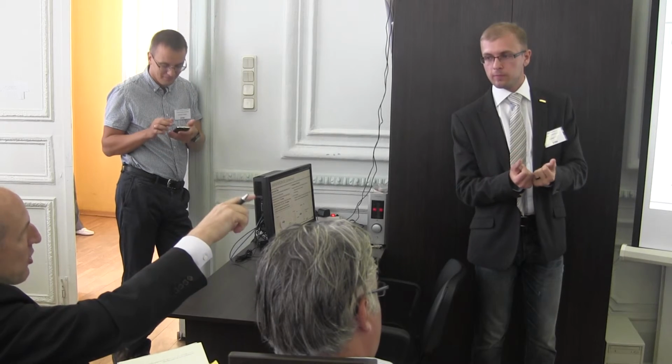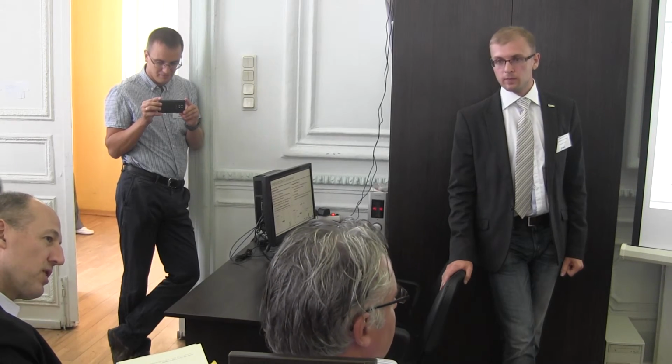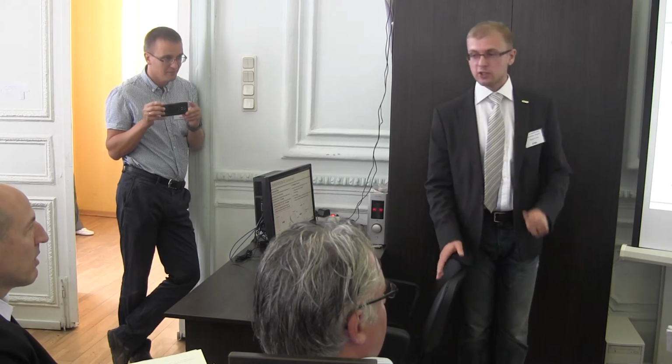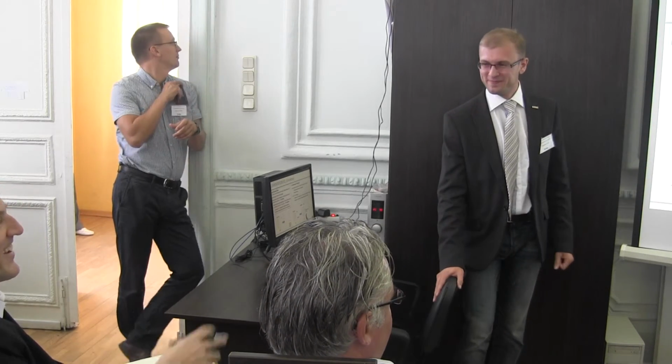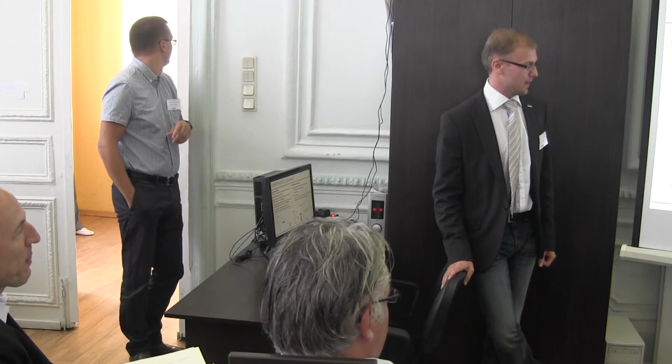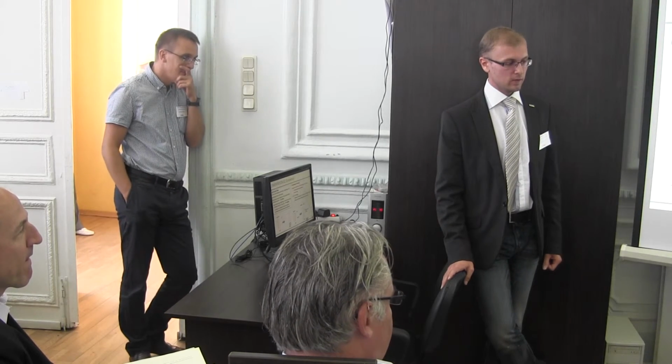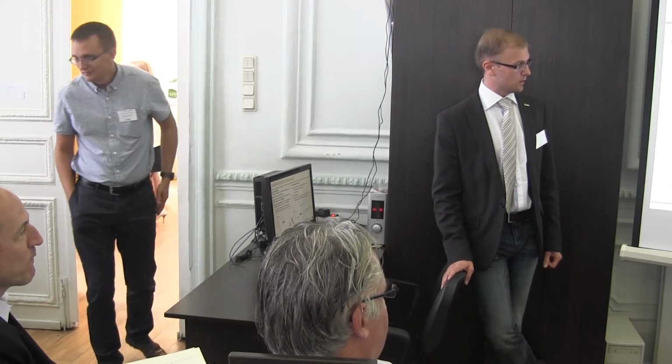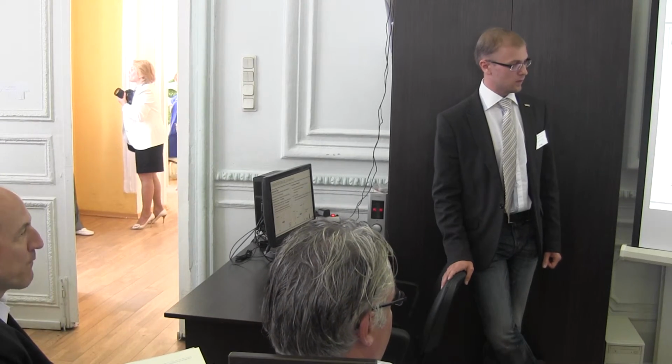So the coating itself luminesces? Yeah. Aluminum oxide, Al2O3, has a quality of luminescence. Yes, and our coating has layers. That's our chief technologist. There are two layers here. First, we do plasma electrolytic oxidation in alkaline solution without anything that contains silicon.